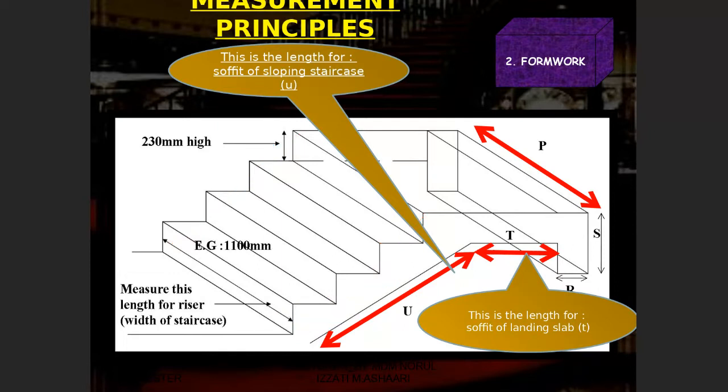So we have finished number 1, that is riser. This is number 2, that is string. Now we move to item number 3, that is formwork to edges of the slab. Formwork to edges of the slab has a similar clause as riser, F1.2.5.